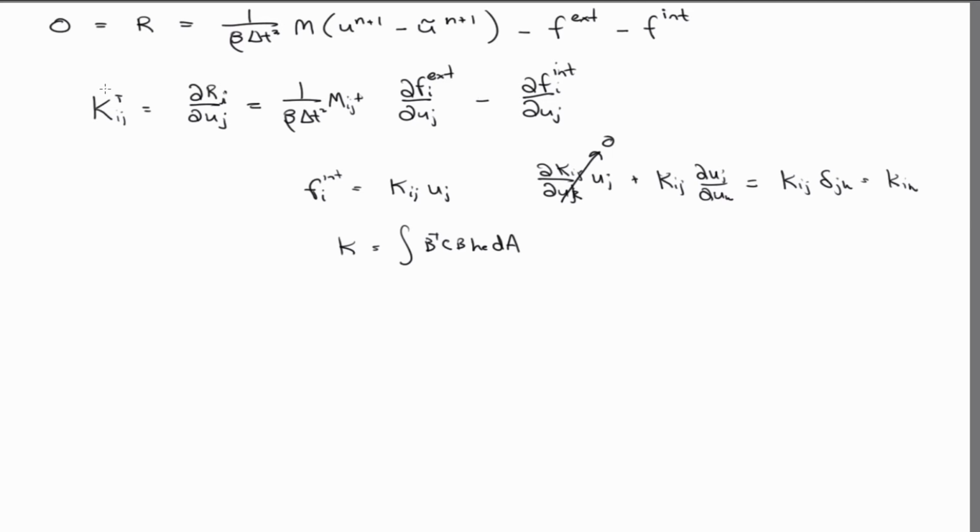No, this is not like a quasi-static or a dynamic relaxation. This is actually an implicit method. Right? So you'll have the dynamics of the accelerations in there, albeit at a lower frequency because of the damping.